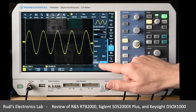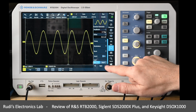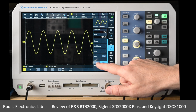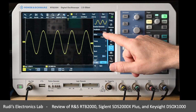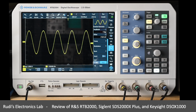Changing this particular thing here, the only thing it does, and you can actually see it happening here, is change the values that are shown on the oscilloscope as the output voltages. It halves it, assuming that the 50 ohm output will be loaded with a 50 ohm load, and that halves the amplitude of the signal. So the only thing it does is change the numbering and divide it by half. And that's the case here for all the devices. So there are not really different output impedances, this is just changing the shown value to reflect the load.